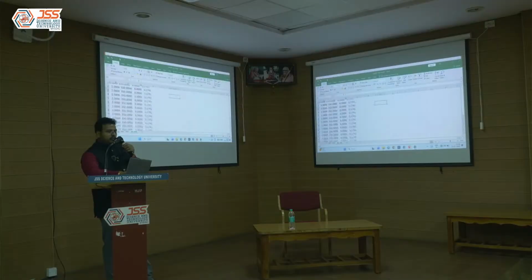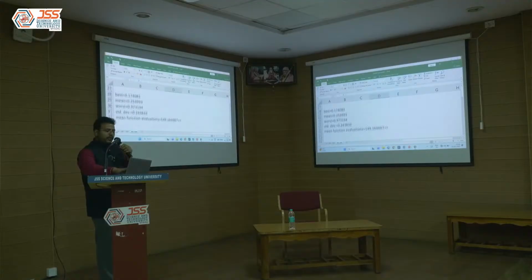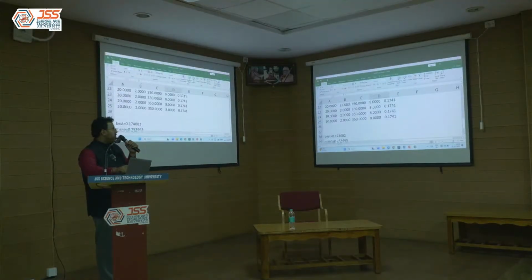when we combine both also, we have studied how the parameters are varying and how the response is coming. In my case, I required surface finish higher the better, and MRR higher the better. So I combined both the equations and gave input in the coding, and when we run it, it will give you some best solution: when you use 20 kilohertz frequency, 350 mesh size, 8 minutes processing time, and 2 bar of pressure.